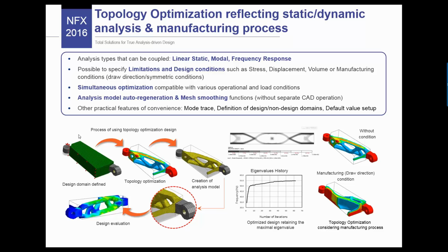If you're not familiar with it, what it does is that you give the software a certain design volume, then you give it some boundary conditions and loads that you would apply to your model, and the software will automatically optimize the mesh density of your model in the areas where you have the highest stresses. Then you get a part which is optimized by the software.